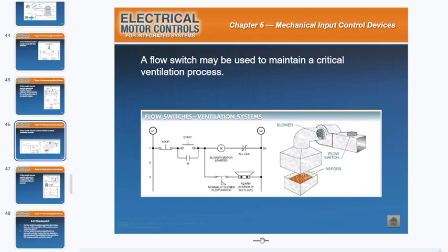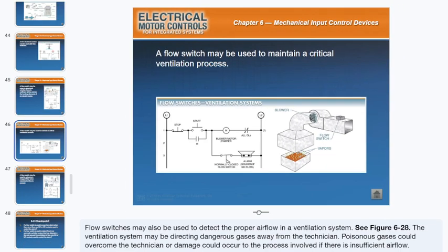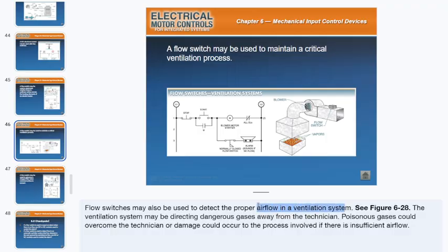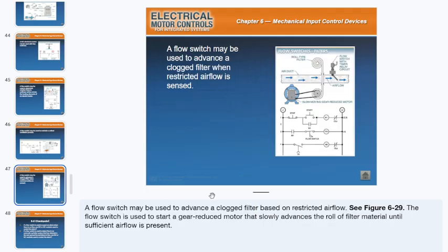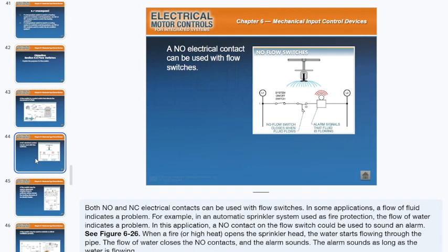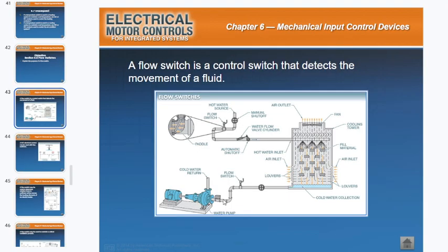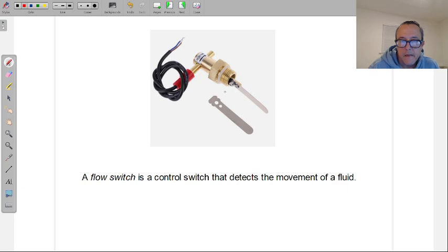They have a couple here that they're showing us. Like for vapor and airflow, I've never worked with an airflow one of these. Plenty of liquid ones, water treatment and pumps and all kinds of stuff. So yeah, I'm not too familiar. I'm more familiar with the ones that are over here, right? For something like that, like this image that they have here. This is for a water pump. So you have a flow switch and it senses, all right, water's coming in or water's leaving. And this is what they look like.